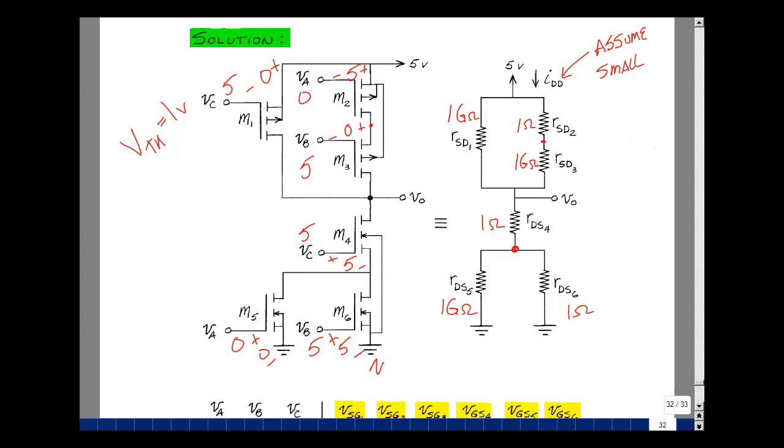Solve for V out. It's going to be equal to 5 volts times 1 in parallel with 1 gigaohm is roughly 1 ohm, plus 1 ohm is roughly 2 ohms. And likewise in the denominator, we've got 1 gigaohm in parallel with 1 gigaohm, about a half a gigaohm. We've got 10 divided by roughly half a gigaohm, something that's very close to 0, something in nanovolts. Let me erase this so we can do the next case.